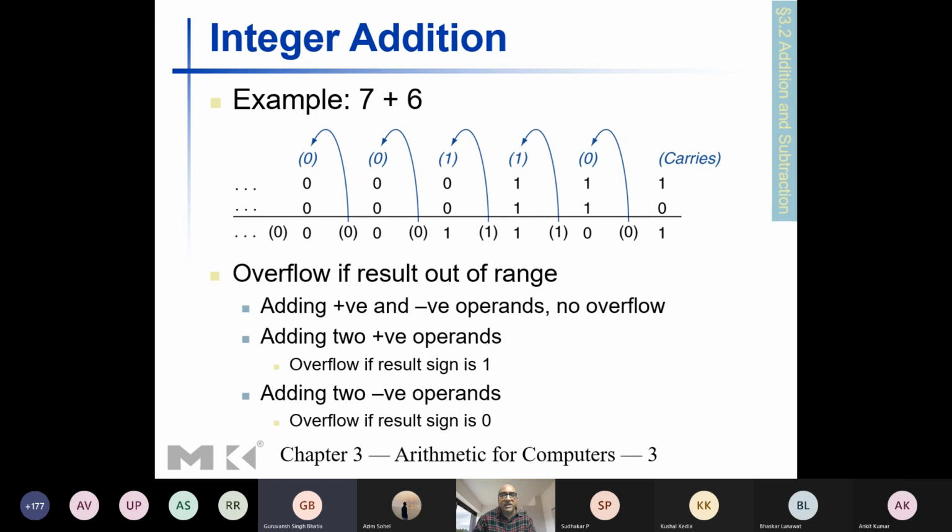In case of 2's complement, if it is 8 bits, 2 power 8 possible values will be there. That is 256. Out of 256, 128 values, that means 0 to 127, positive values will be represented, and -1 to -128 will be represented. The total will be -128 to +127. That is the total range accommodated by 8 bits in 2's complement notation, as we have seen.